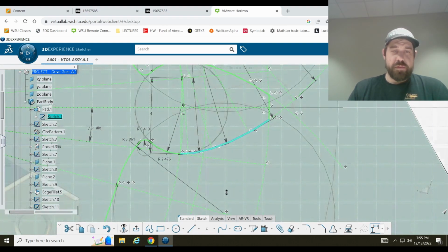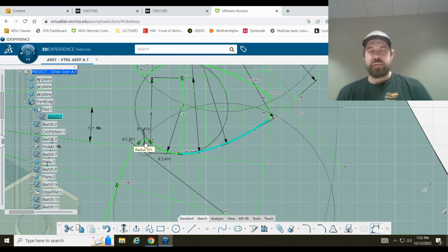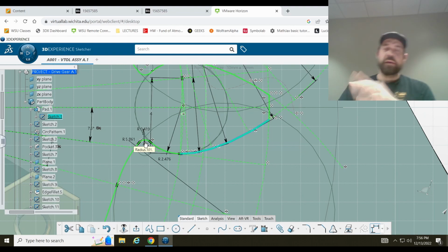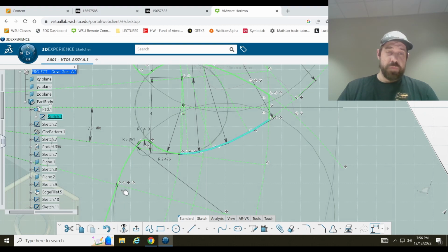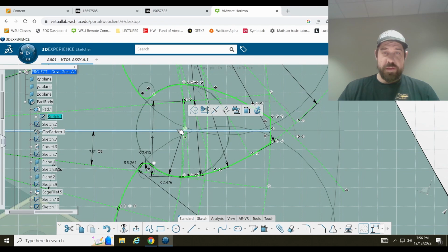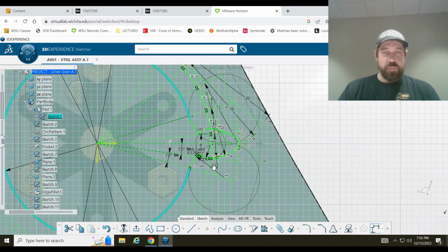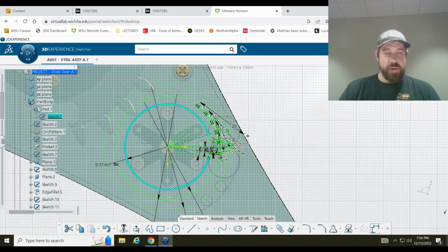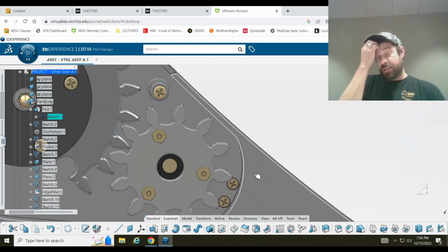So we take that, and the bottom part of this is really inconsequential. This isn't where the teeth of gears actually interact. This is just to make a nice smooth transition between gears that goes down to our base circle's radius. So we take this profile, we mirror it across this line to get one full tooth. We smooth that into our base circle there. We extrude that pad and we radially copy it the number of times that we need teeth. That's how we get the drive gear.